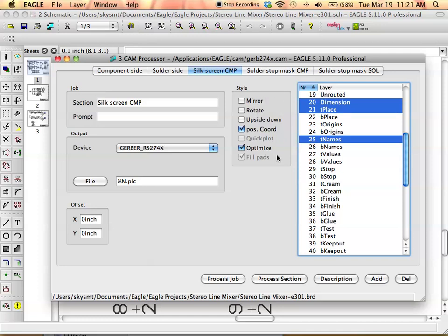That, I guess, is useful for some applications. I haven't found a time when I needed that yet. I have accidentally done it and had some of my Gerber files mirror imaged and some of them not mirror imaged. Okay, and so that's our next thing we're going to look at: viewing your Gerber files to make sure that you've done them right.